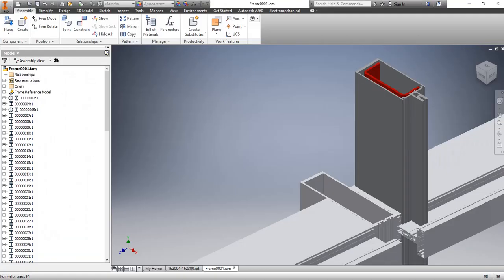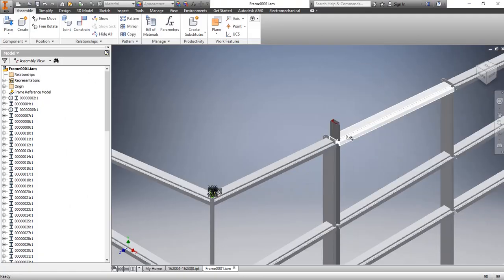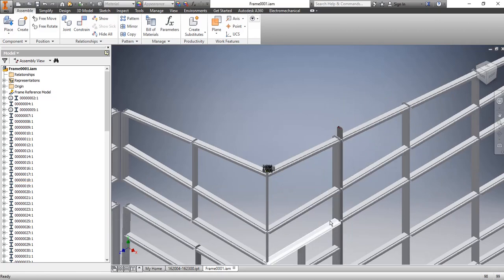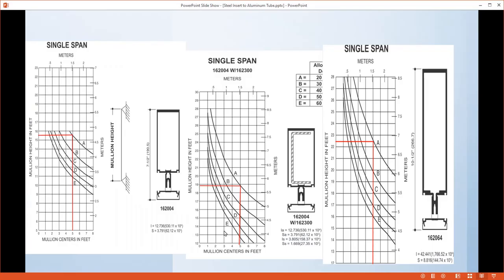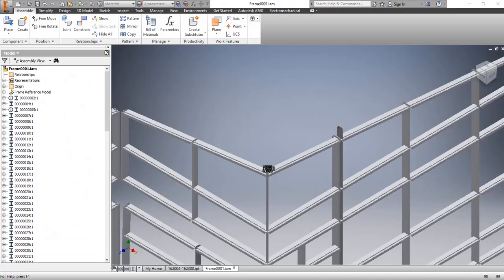That is not satisfactory for this situation because this one is 20 feet. Then if we put in insert steel, with the same 5 feet spacing, you can go up to almost 19 feet. So this is close, but still a little short.